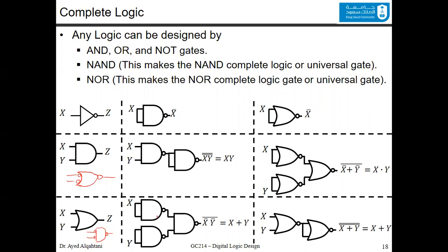Now, since we here want to generate NANDs, you can see that there is a NAND already here, and this NAND is this one. And this bubble, or what we call the inversion, will be 2 inverters designed by the NAND that we have here. You can have the similar observation when you try to prove the NOR is universal and you convert the AND to only NORs.